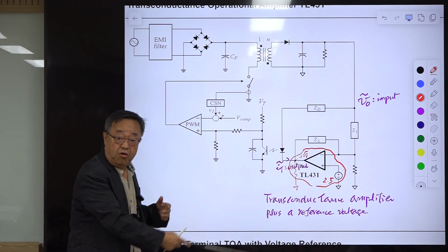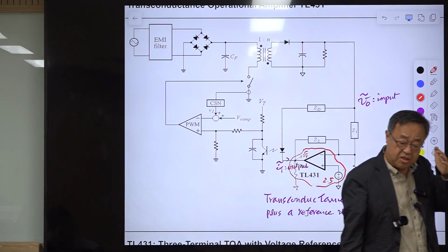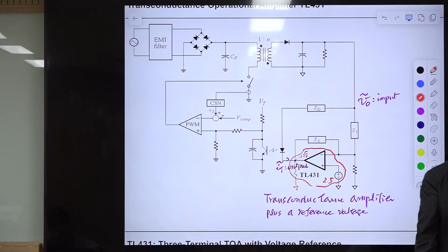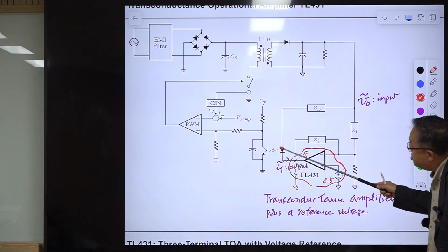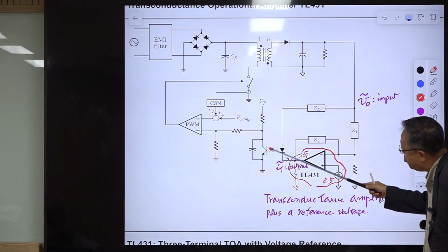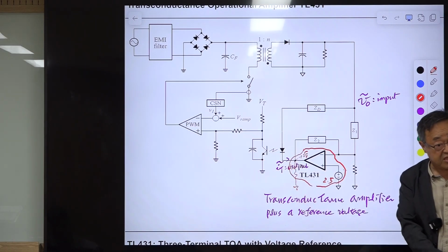Okay, so output does not simply mean what is located at the output. Output is the signal we are using for our purpose. You are extracting this current, and the current is transmitted through this optocoupler and used as the feedback signal.